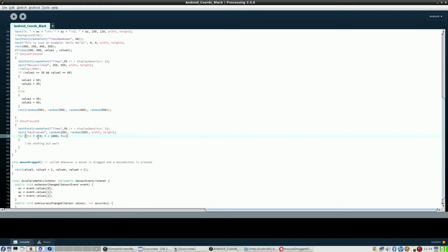The delay didn't work at all, so now I am trying to do something which has been used for a long time: a no operation. You take a for construction, starting at 0, while smaller than 1000, add 1 to the value of i.